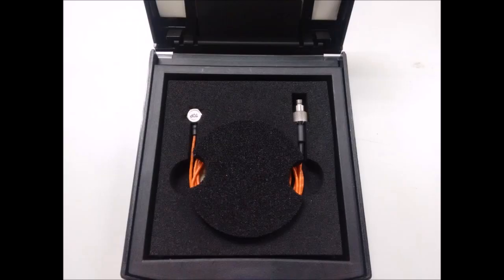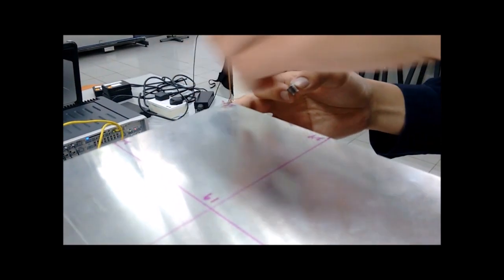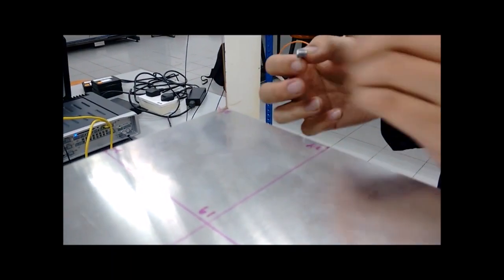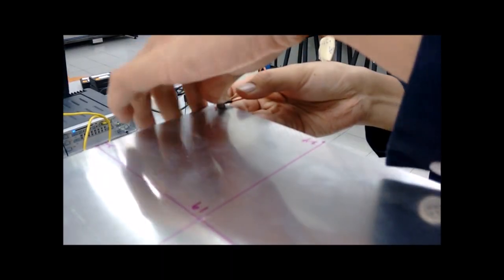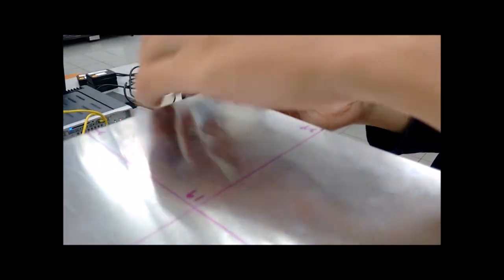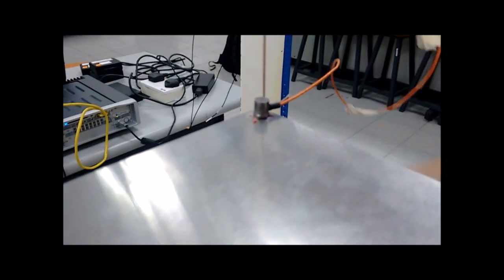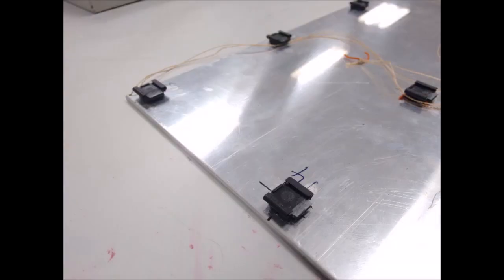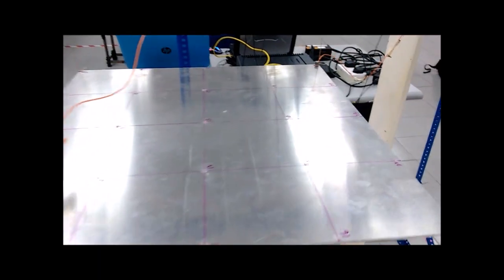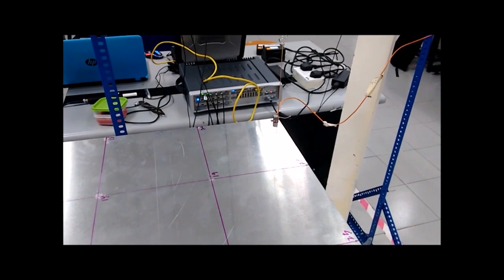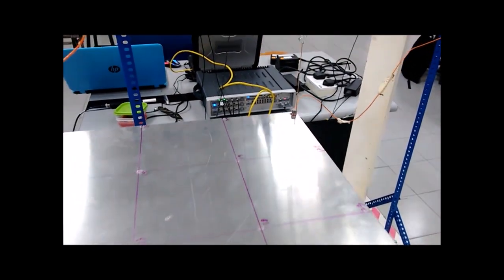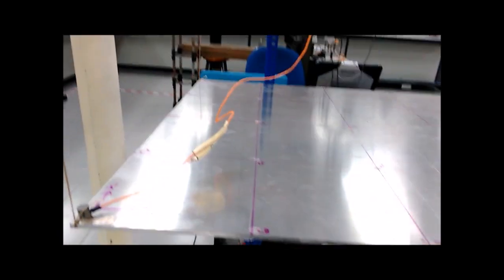An accelerometer is used to measure the acceleration introduced by the structure vibration. The accelerometer is attached to the structure at the particular node that we are going to measure by using petroleum wax. Other than petroleum wax, a plastic stud can also be used to attach the accelerometer. An impact hammer test is used in the experiment. 2 roving and 1 reference accelerometers are used to measure the vibration.